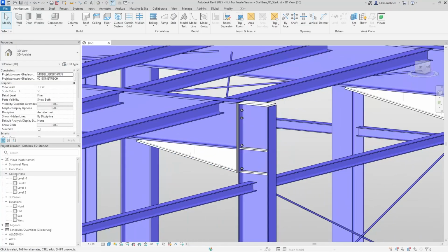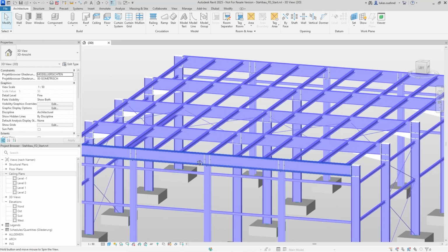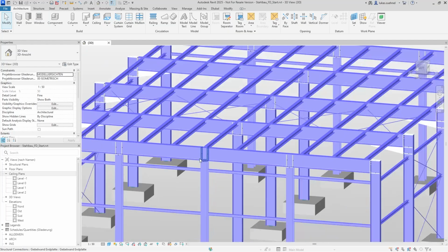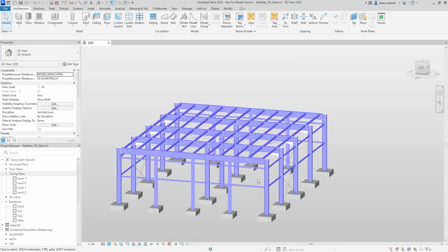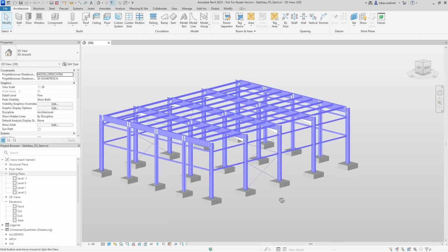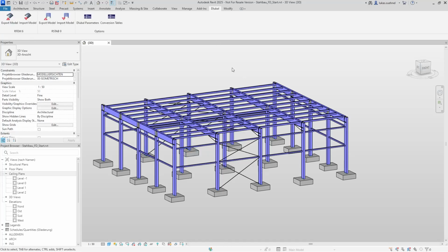Some of the joints already have been defined with an end plate and some bolts, or here you can see that the columns are connected, hinged to the beams. So some details, I just want to mention it. It will be more relevant when we create the analytical model afterwards, or when we talk about the data exchange via IFC. Yeah, that is the model, and the plan is to help the structure engineer by exporting it to Rfem 6. For the export to Rfem 6, we can use our Dlubal plugin.